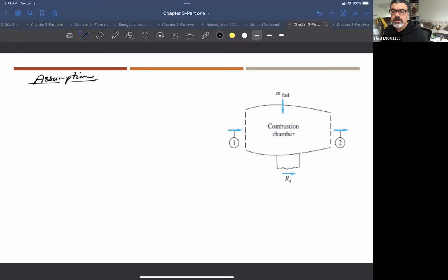What is accumulating or what is changing inside this system? This system is running all the time, right? So basically we can assume steady state, because most of these open systems with flow in and out are steady state. Most of the time, unsteady is talking about a tank filling or something like that, right? But in these cases, there is going to be a steady state.